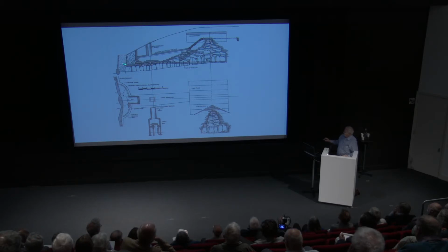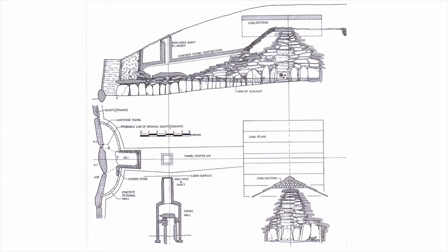And you can see that where we have extraordinary pressures in Newgrange in Ireland here, they have used extraordinarily large lintels. But those lintels are not supported on the passage uprights. They're supported on the cairn material outside. So they're bridging structures within which you can have a sort of fancy pants. It's mimicked, in fact, in concrete here in the modern relieving structure that was put in during conservation when I was a child.